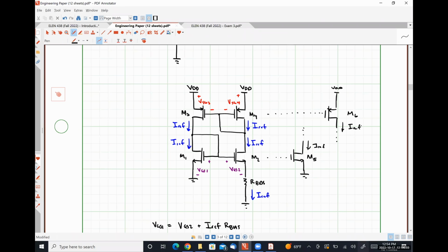Another advantage here, and we haven't listed any sizes in particular, but we're not required to make our PMOS transistors very, very large if they're serving as a load here, like we did in the MOSFET biasing. When we did the MOSFET biasing, we had to increase the length of our devices to accommodate that extra voltage. The resistor takes up that extra voltage in this case. So we can use the minimum sized NMOS devices, and then we just need to scale our PMOS devices by a factor that effectively makes the mobility effects the same.